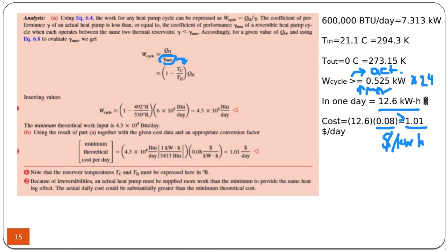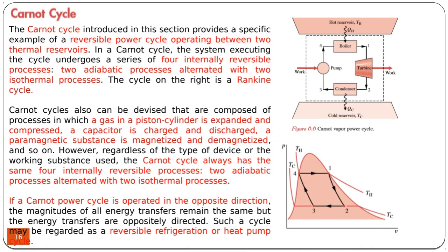So the Carnot cycle has four reversible processes. The reversible processes found in a Carnot cycle, and we are talking about the Carnot heat engine, are two constant temperature heat additions and removals and two adiabatic compression and expansion. So what happens inside the boiler? It's a heat addition at constant temperature. As you can see, heat addition takes place at constant temperature.